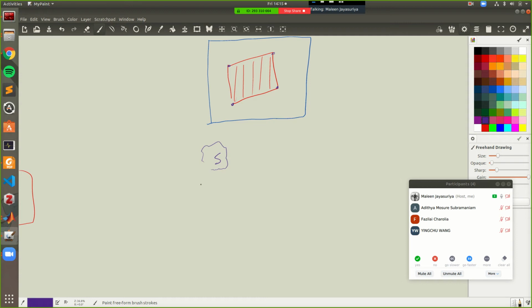Which can encompass any sort of detection, any sort of feature that we are interested in. S can even mean, for example, 3 of these all together. That can be one feature. Or for example, if you're dealing with a person, maybe you have a really good eye detector that detects the whole eyes of the person. So that will be your S in that case. But to make things simple, let's take each of these corners as your S. So that is what we are currently detecting. S star is where we want those features to be.